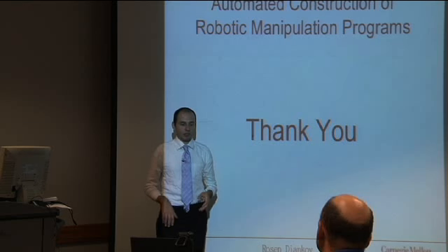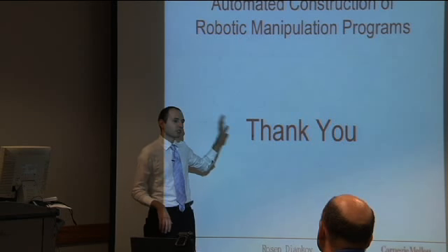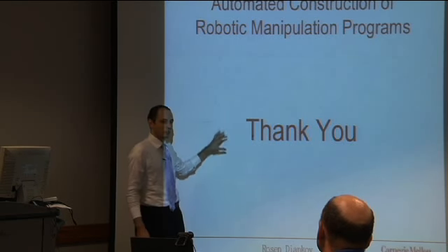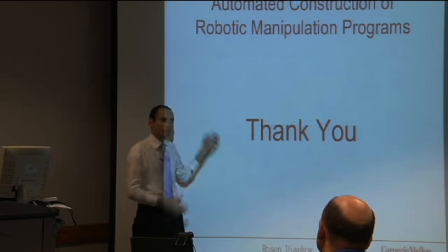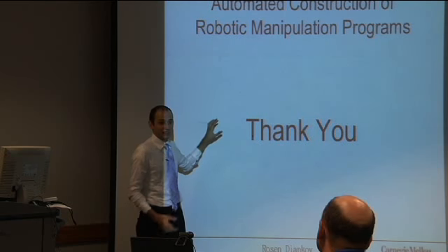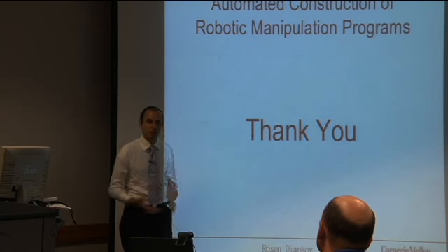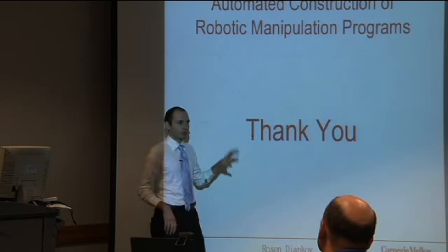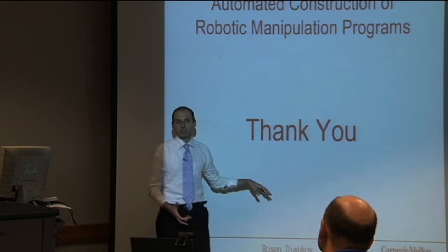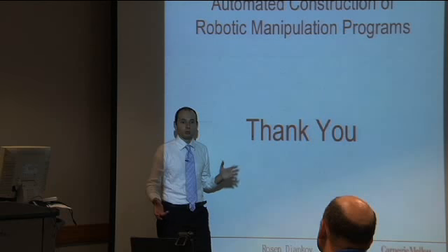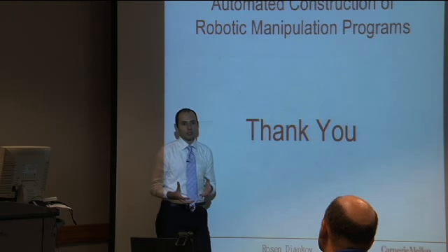That's one of the reasons why you see this division between the user input, which people with sufficient knowledge in robotics and industry can specify, like CAD models and training data for images, and then the analyses, like the inverse kinematics generators, the reachability, the detectability extents, and all the parameters for those.